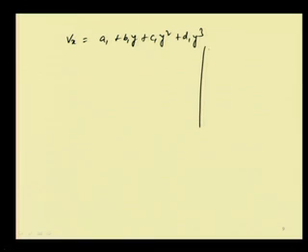Now, again with the standard practice, we take a velocity profile of this kind: Vx equals a1 plus b1 y plus c1 y square plus d1 y cube. We have seen this kind of analysis previously also. Here the conditions are, at y equals 0, Vx is equal to 0.